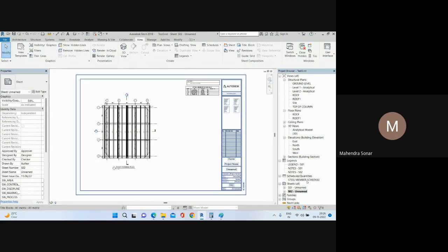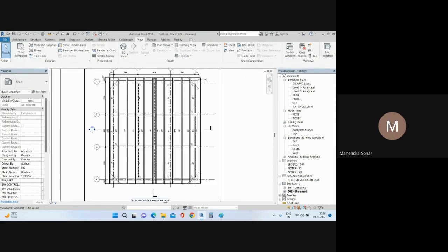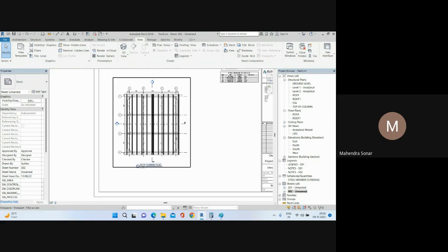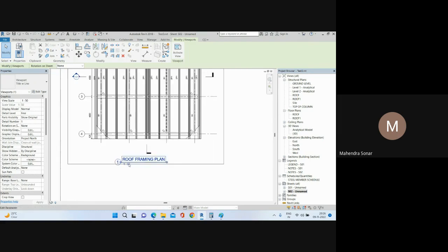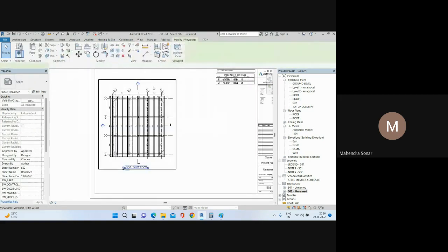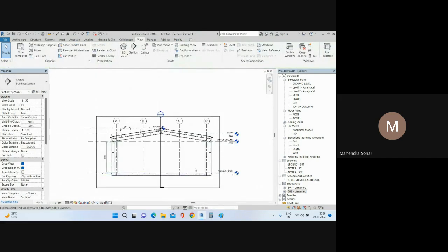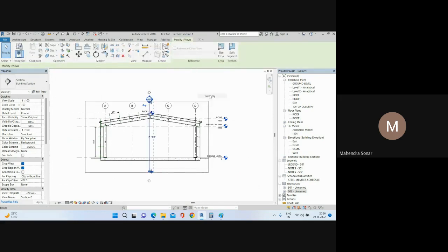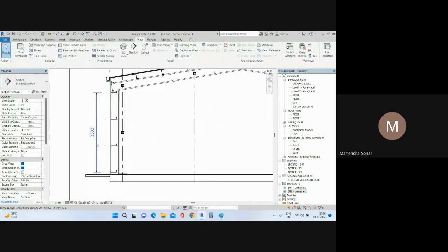Then next drawing, you need to add your elevations, all four elevations, right? So how to create elevation? Okay, so I think on the next drawing, if your section fits in this drawing, you can add. This scale is 1 to 50, and if you have two sections, okay, go to view. So this is your sections, right? So you need to clean up this. Okay, so hide all sections, then labels. Don't give the labels. We will give the top of concrete.